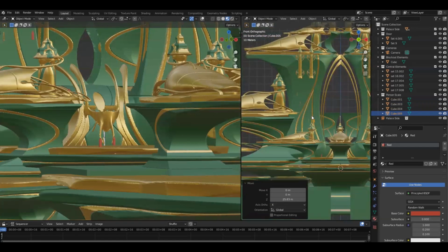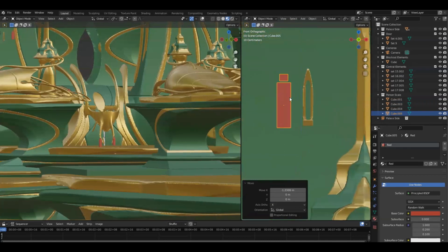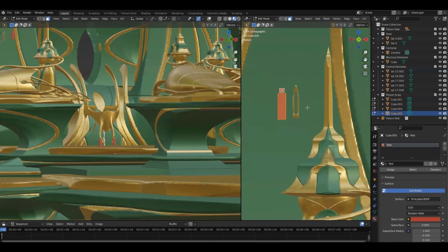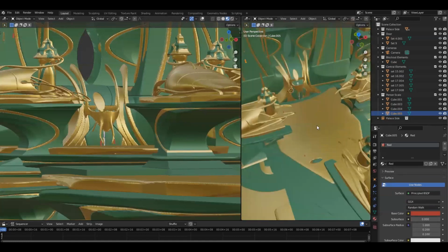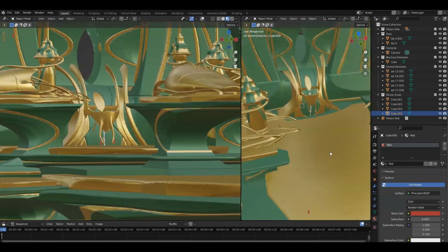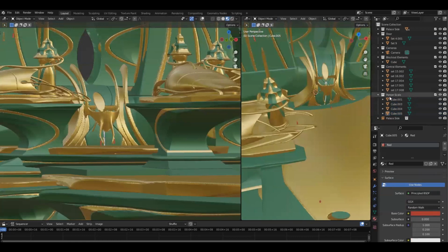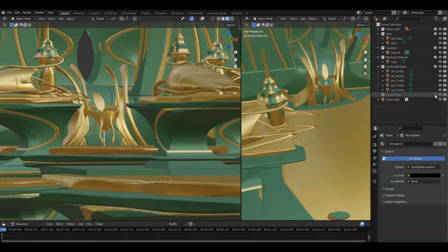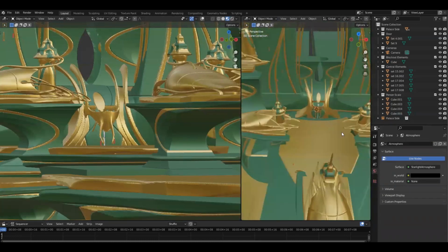And if it's not working, which it looks like it's kind of not, because this is a little bit the wrong proportion, I can always just go into edit mode, hit A to select all the faces, and I'll scale it down just a smidge so I could see like a person's kind of looking out that window. And because we're doing it this way, it's going to change all the other humans accordingly. So that's a nice little trick, and I'm going to be doing that quite a bit. And then they're also all in the same collection, so I can just close that off and turn them off if needed. And yeah, I think that scale is pretty cool.